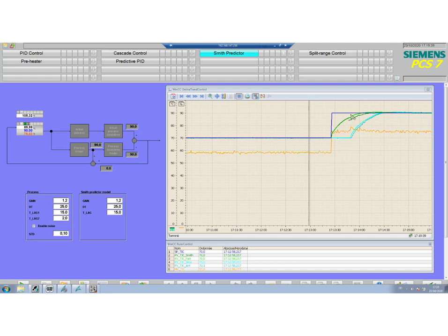In the beginning of the response, before the delay, there is no difference between the predicted PV and the PV that is coming out of the fast model. And here at some stage, after the delay, the model reacts as a first order system. Okay, this is normal, and the process reacts as a second order system. So here the slope initially is 0, right?